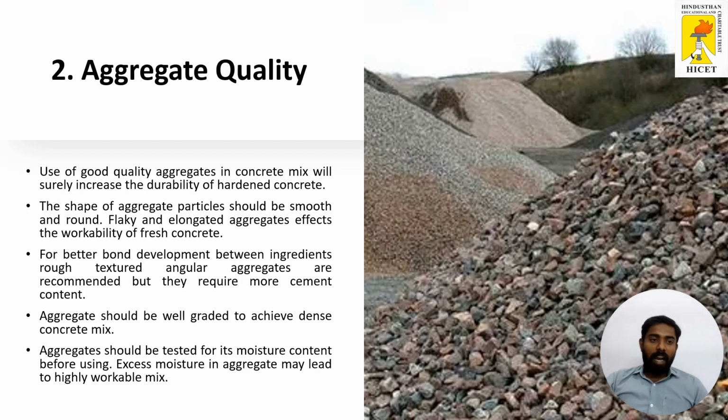Next one is the aggregate quality. The use of good quality aggregates in a concrete mix will surely increase the durability of the hardened concrete. The shape of the aggregate particles should be smooth and round. Flaky and elongated aggregates affect the workability of the fresh concrete. For a better bond development between the ingredients, rough texture angular aggregates are recommended, but they require more cement content.